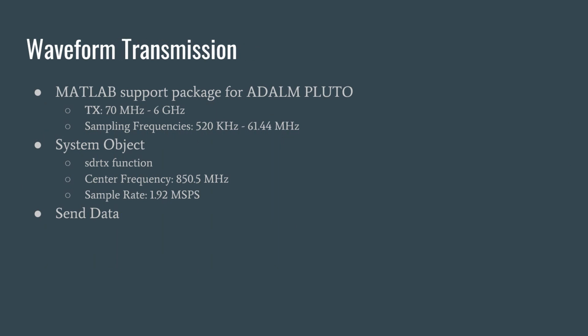The waveform transmission was achieved using the Adalm Pluto SDR and its MATLAB support package. MATLAB provides an input-output abstraction for the Pluto communications. To achieve the setup, a Pluto system object had to be created in MATLAB. The center frequency of 850.5 MHz and sampling frequency of 1.92 megasamples per second were specified.